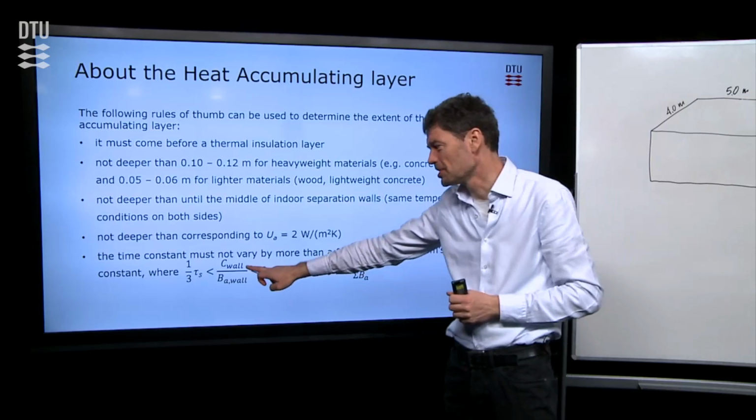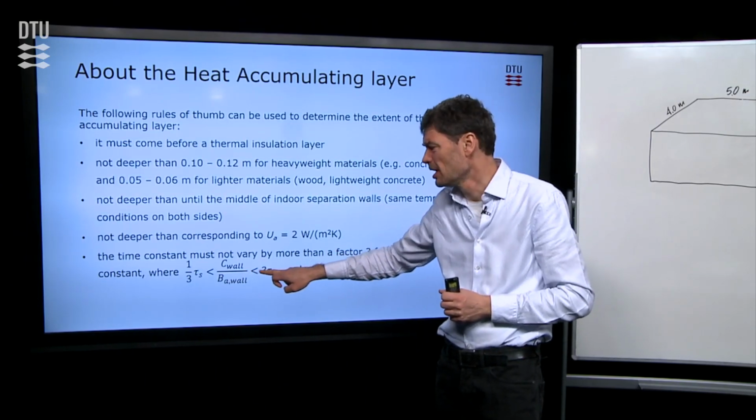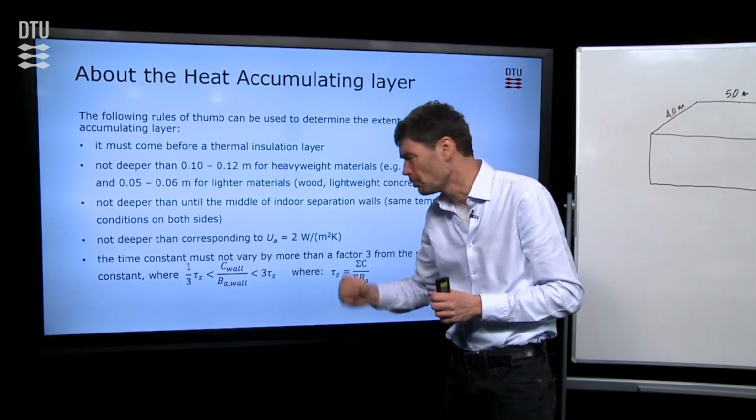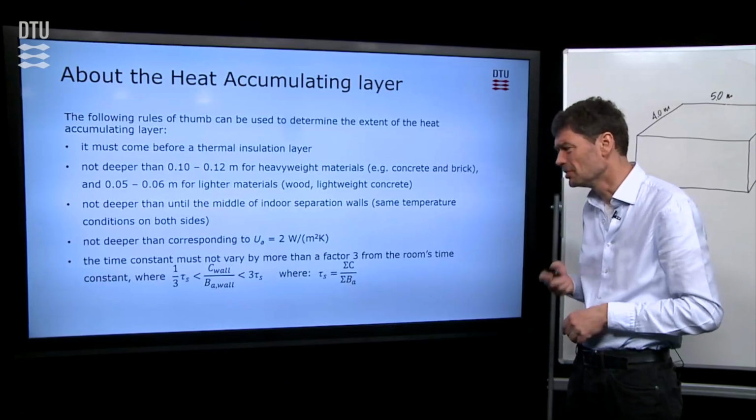So for each wall or material, you can calculate its contribution to the time constant. And it should be not more than a factor, say 3, less or more than the average, or the time constant for the whole room.